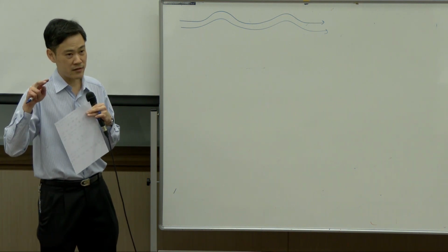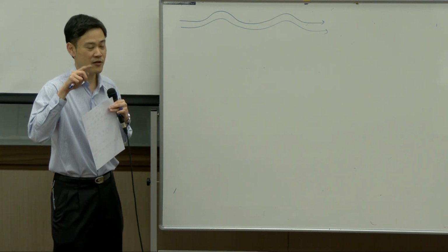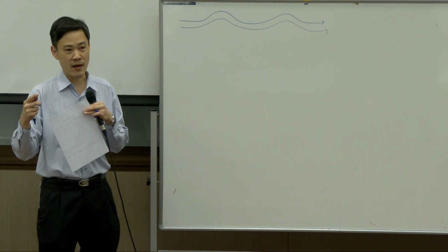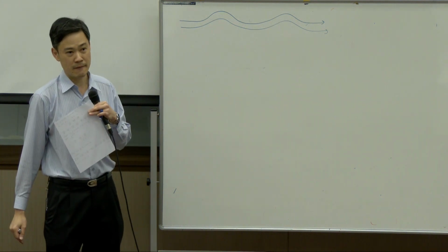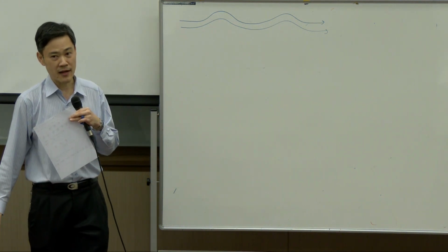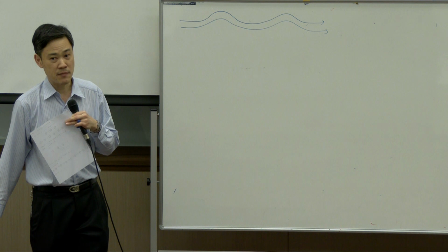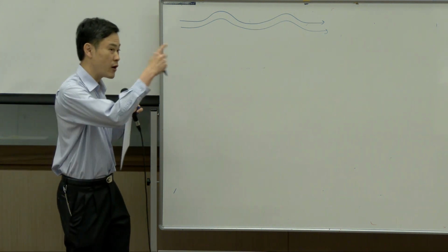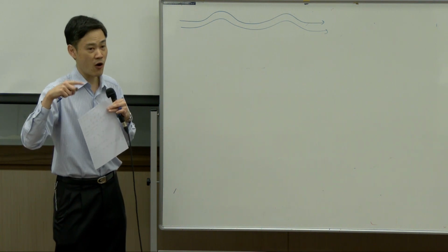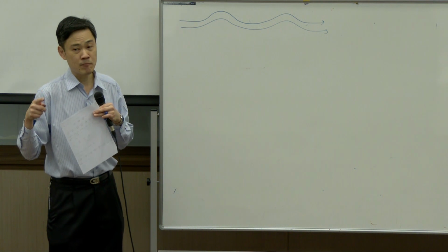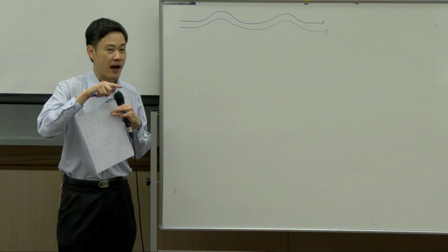The word turbulent in your mind, I know that it is clear in your mind, means the streamline is not linear, it's not constant, okay? But I want to be clear that the term constant is not limited to constant with respect to position. You may have swirling, but still be laminar. It doesn't mean turbulent would always be swirling, okay? The term turbulent means that velocity is a function of time.